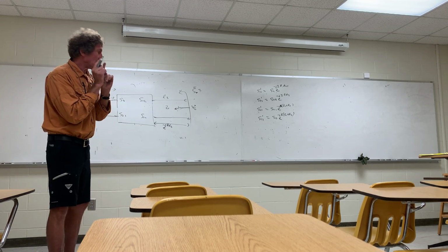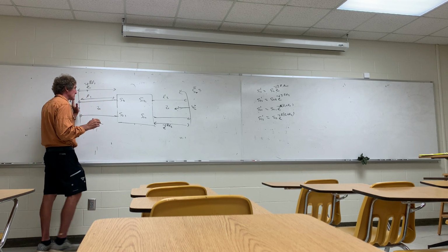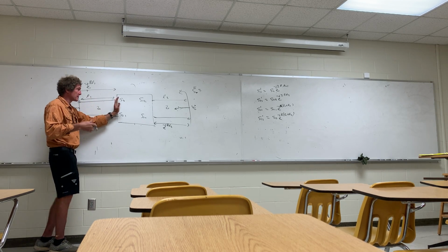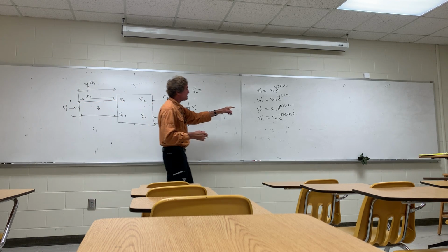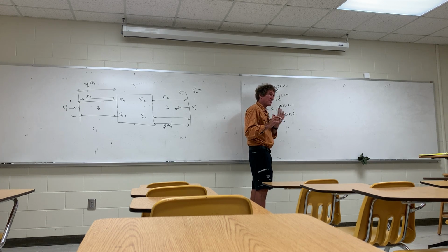So you write an equation for the S parameters, but we had to use a shifted reference point, because our equipment, our network analyzer, came with cabling that's longer. So the length of the cable you have to work into, right? Now you'll notice these values of beta here. Beta is 2 pi over lambda. Follow? It's not a constant for all frequencies.